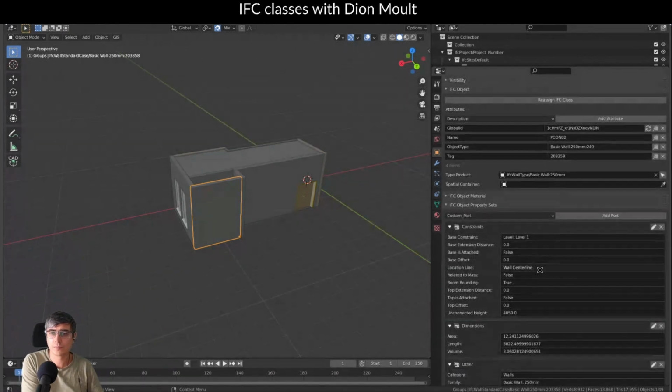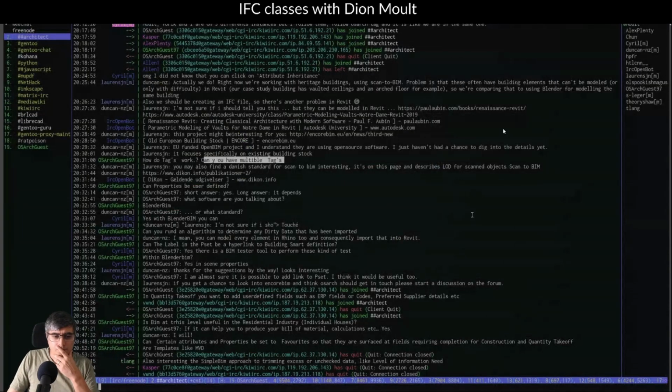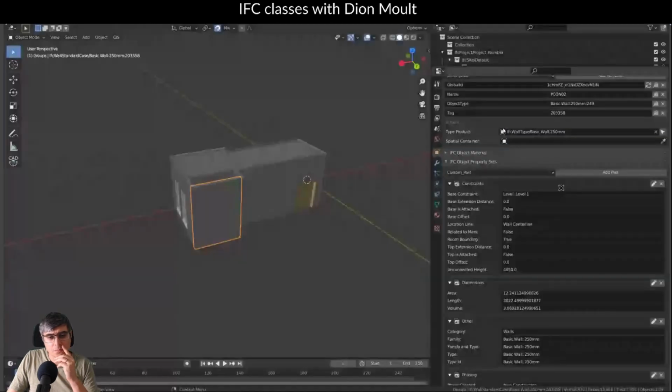And that's the same with property sets. You can only have a property set once. You can only have a property once. You're not allowed to define it twice. And that is actually black and white. It's written in the specification, written in code, that you're not allowed to have two duplicate attributes or properties. There are certain attributes and properties which allow you to have a list of values. So in that case, obviously you can have multiple values, but not in this case.